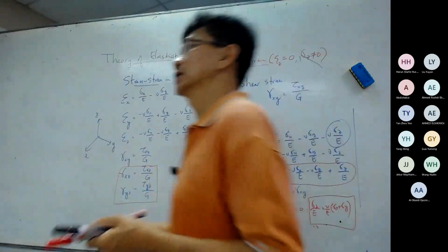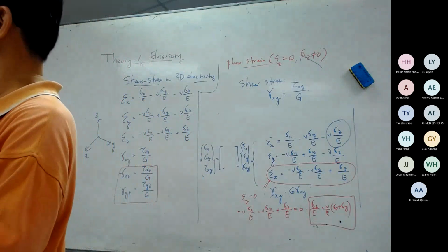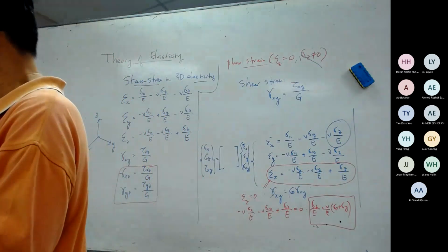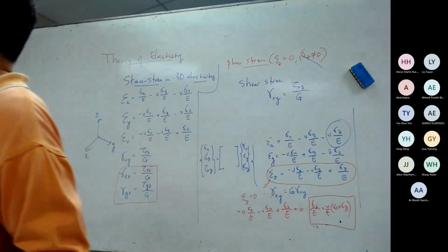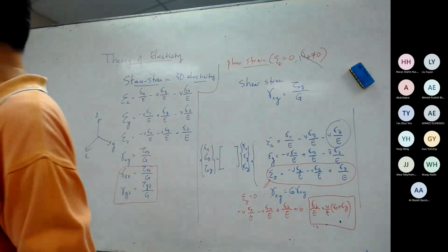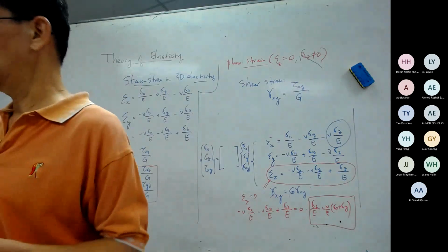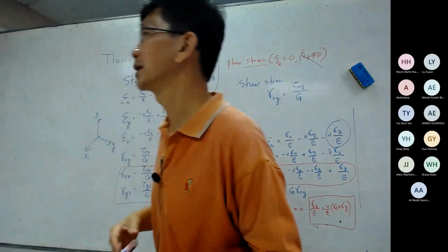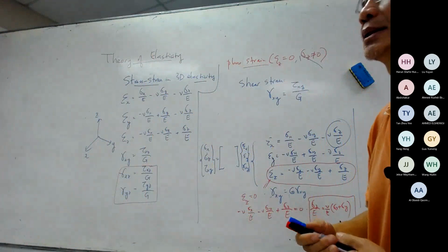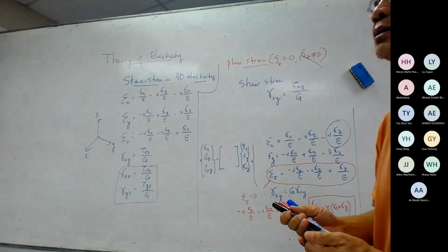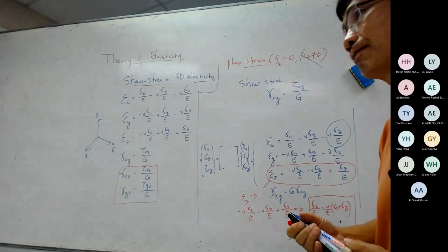So if we derive it from the point of view of change in shape and relate that to the change in angle, in that way you can get the shear strain without G. You relate to the change in geometry, then you can get the shear strain without the necessity to know the material property G.